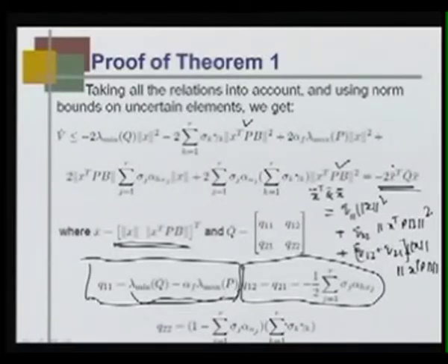I wish that you understood how we finally wrote V dot in terms of a quadratic function x bar transpose q bar x bar. What is the advantage of this? If I can write V dot as x bar transpose q bar x bar, then if q bar is positive definite, since there is a negative sign here, V dot is negative definite, hence the system is stable.